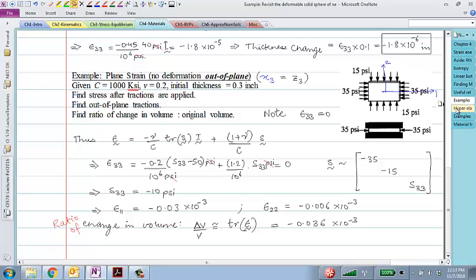Okay, yeah. So let's say this was our dam cross section, and we have dam on the left and the right of it, and maybe on this side I have water pressure building up like a triangular profile. So typically, what would happen is this would be like a tall wall which would deflect, just like a beam. It would deflect as if this was a cantilevered column subjected to a distributed triangular load, and therefore it would deflect. So in plane, it would have deformations, but not out of plane.